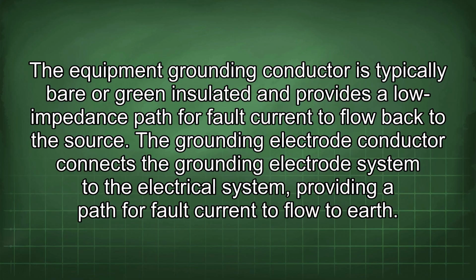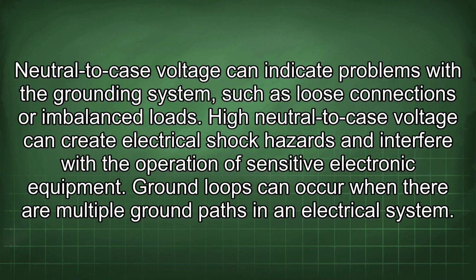flow to earth. Neutral to case voltage can indicate problems with the grounding system, such as loose connections or imbalanced loads. High neutral to case voltage can create electrical shock hazards and interfere with the operation of sensitive electronic equipment.